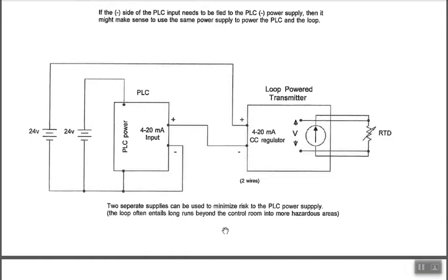And if you want to check the current in a current loop, of course, remember, current's the same everywhere, so it doesn't matter where you would look. You can look here, here, here, here, here, here. Anywhere you want to break into the loop and have a look at the loop current or monitor the loop current is fine. It's a series circuit, current's the same everywhere.